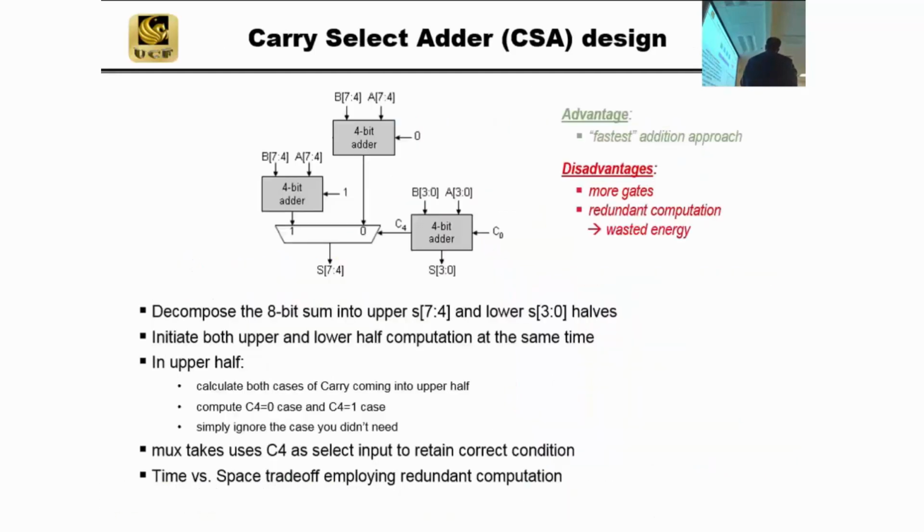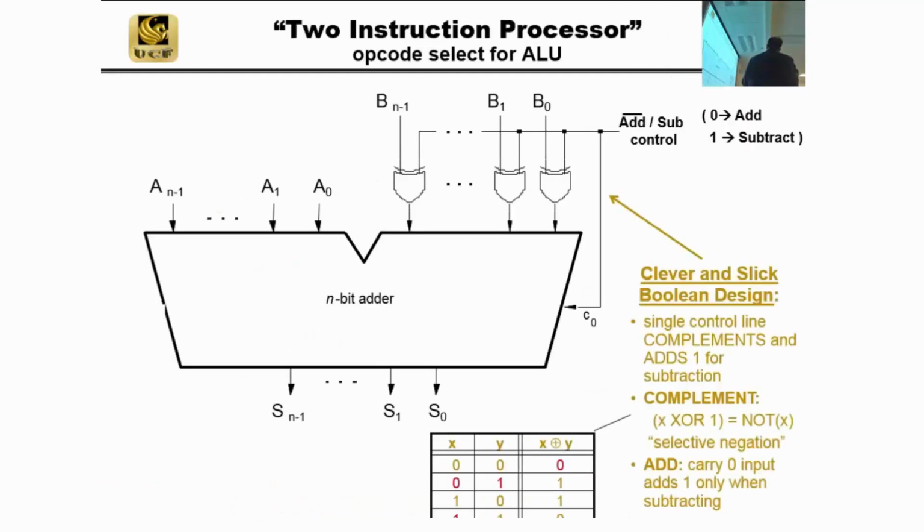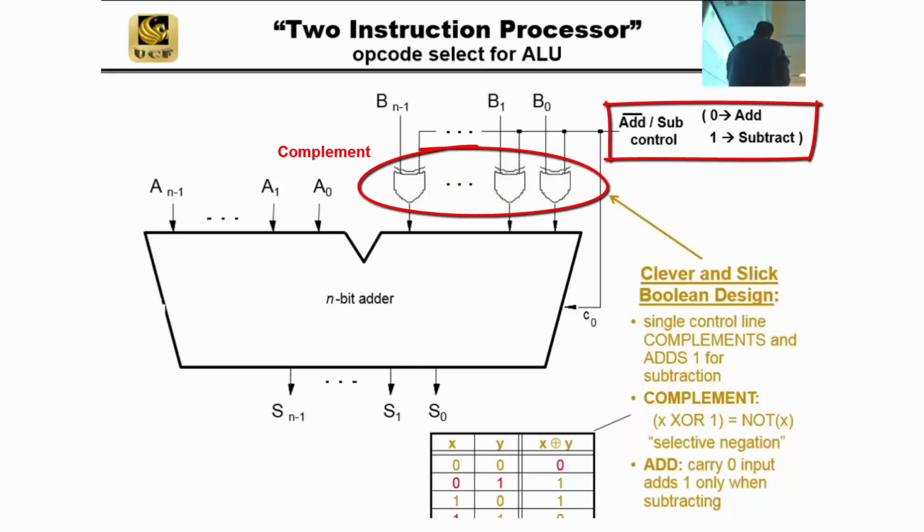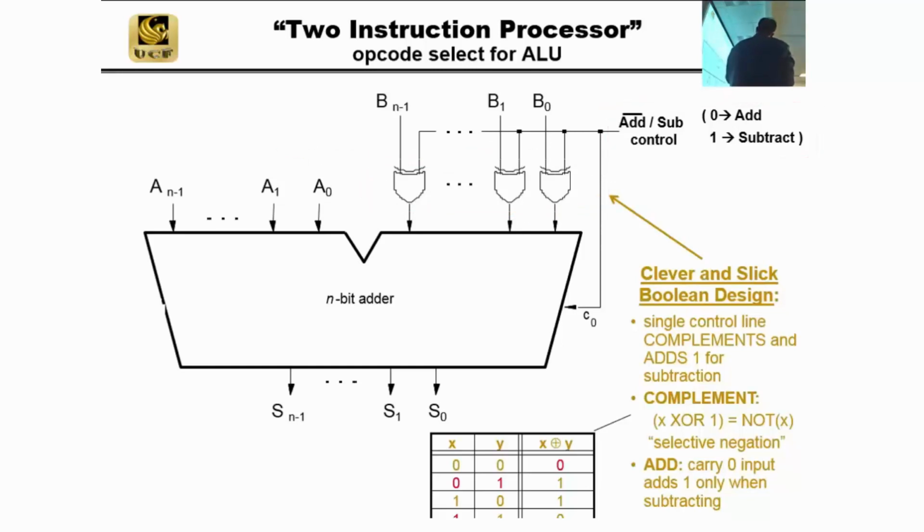But now it's coming in handy. Where's the handiness? Well, if it's subtract, I have to complement and add 1. So this line goes to 1 because I need the 1 function here for this conditional knot of XOR. And then no big deal, just connect it here too, and then boom, you've complemented and added 1. So if this line is set to subtract, it's a control line. See the data path? See the control path? It's only 1 bit control. Gives us 2 choices though, that's fine. We can add more bits. If it's a 1, I'm going to complement and add 1.